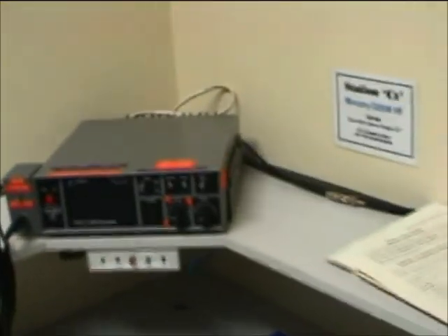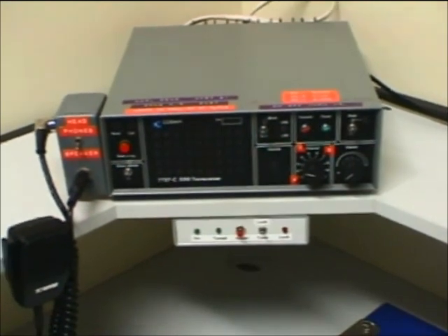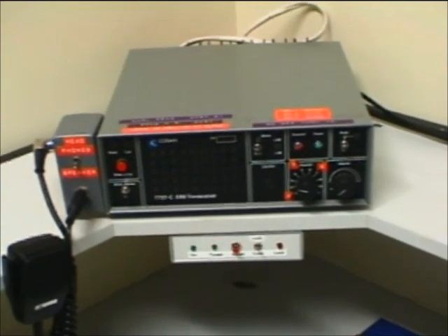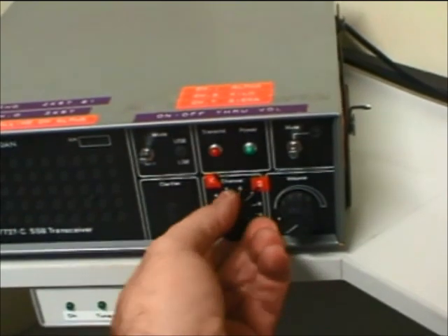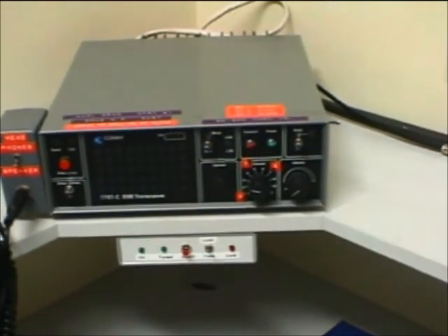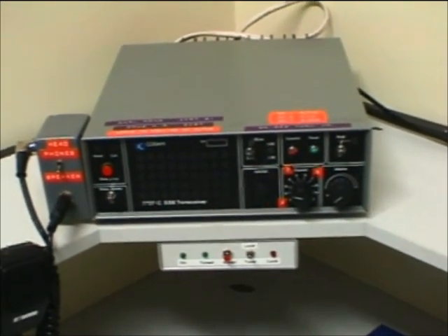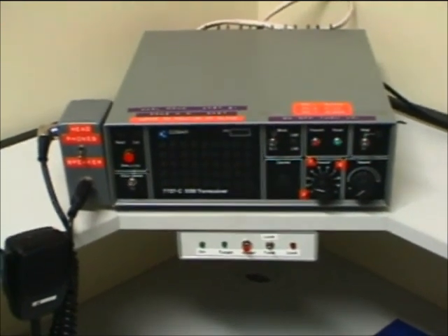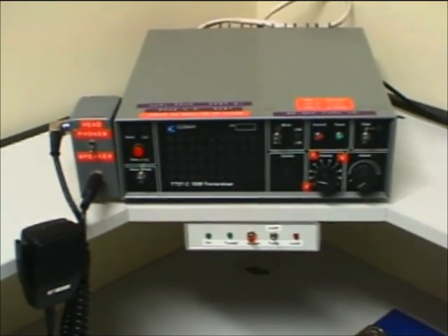Just come around, there's a few more of those VHF ones. And just over here is an older fixed channel high frequency sideband set used for New Zealand civil defence frequencies for longer range stuff around the country. And they use crystal control for the local oscillator to select the frequency you want to operate on. There's a number of quartz crystals inside there that you select, and it has separate filters for each frequency you want for the front end filters, which are selected as well while you switch that. So I think that just gives an example of some of the equipment we have around on high frequency and VHF and so on.